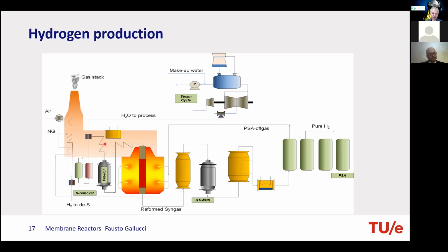And then normally if you convert at very high temperature, you get CO. And CO, carbon monoxide, you can convert further to hydrogen. So you decrease the temperature and you go to water gas shift. And the water gas shift is at low temperature because it's an exothermic equilibrium reaction. So you want to go to lower temperature. And then, of course, you have to purify hydrogen. And if you have a very big plant, then you try to recuperate all the heat, and especially the off gas you use as fuel in the burner.